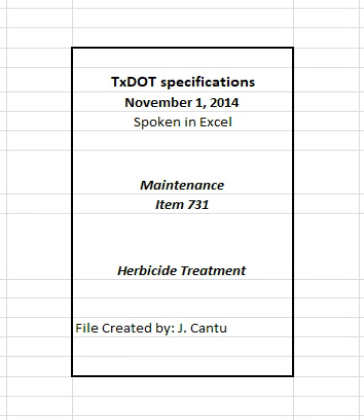7.4 Cut stump treatment. Cut plants parallel to the ground, not to exceed 2 inches above the ground line. Apply the herbicide solution with a low volume, low pressure sprayer which thoroughly wets the area adjacent to the cambium and bark around the entire circumference of the stump. Thoroughly wet the sides of the stump, but not to the point of runoff. Make the herbicide application within 1 hour from the time each plant is cut. Dispose of removed materials and debris at locations off the right-of-way in accordance with local, state, and federal requirements.